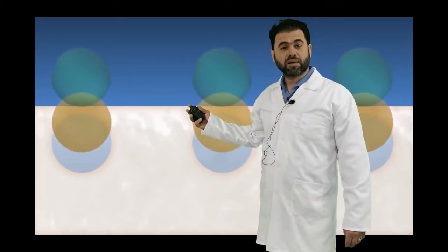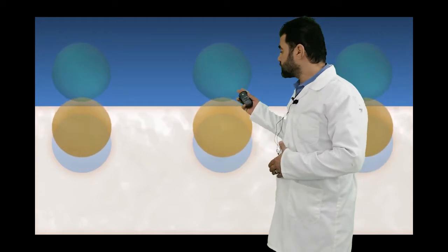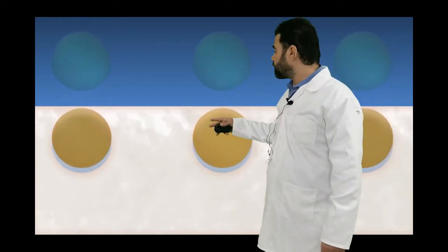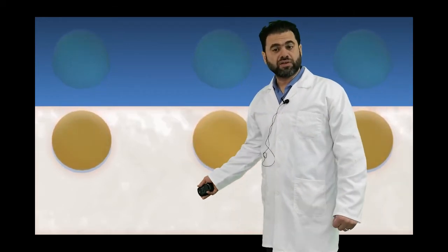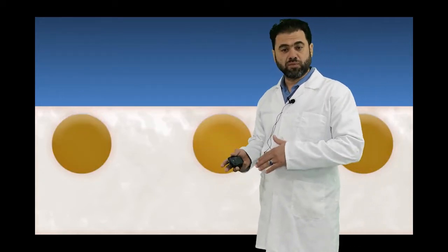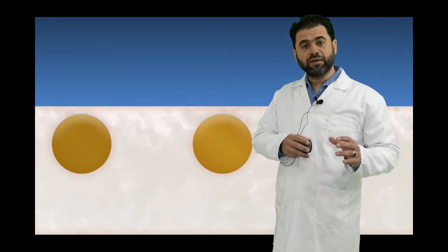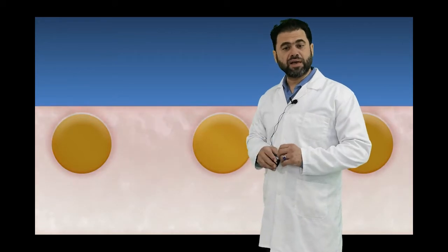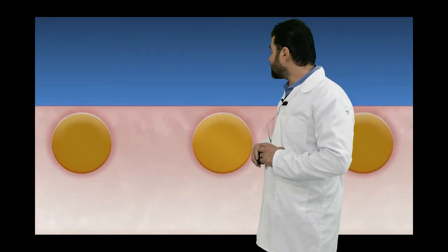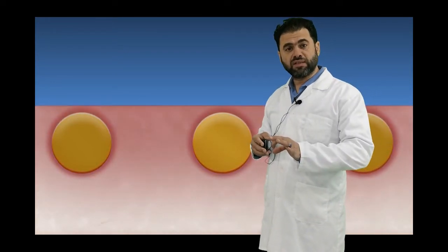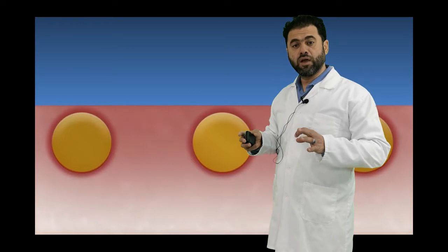So when a ceramic restoration is placed in a molten potassium nitrate, let's put it in a pot of potassium nitrate and heated to 450 degrees centigrade, now the potassium will take the place of the sodium. The sodium will go out and a bigger potassium will come inside and take that smaller space which was occupied by the sodium. And the potassium will force itself in there and it will start making compression.